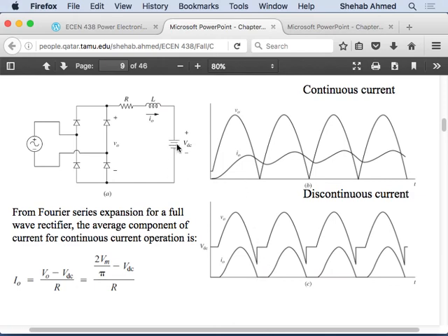So this circuit can be operating in continuous mode like this if I have a small value for DC and a significant hefty inductance. Right? Now I keep everything the same, but increase the value of the DC source. If you increase the value of the DC source, what will that do? We said it will bring the intersection at which the voltage across the inductor is equal to 0 to the left.